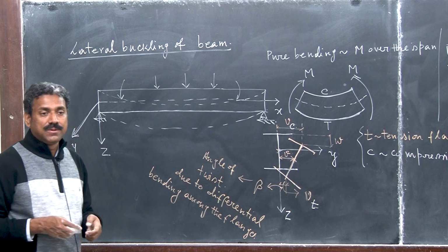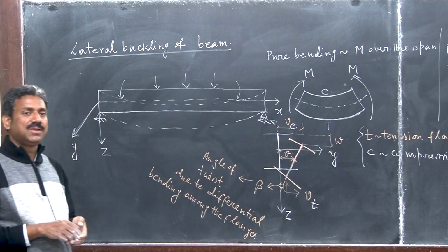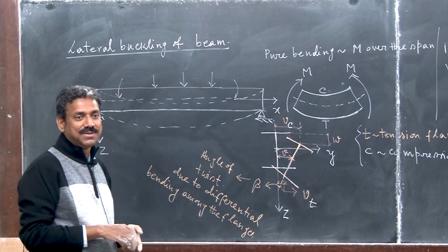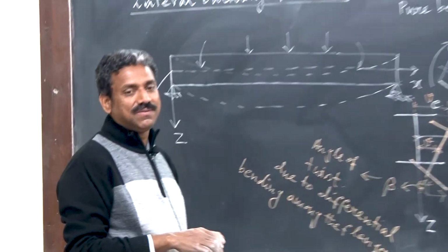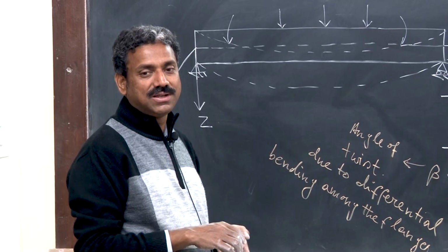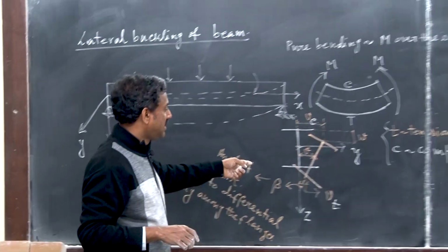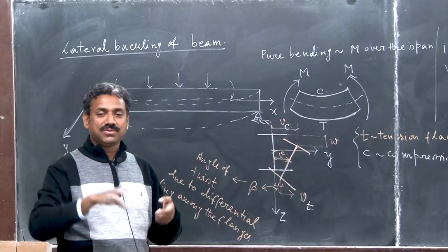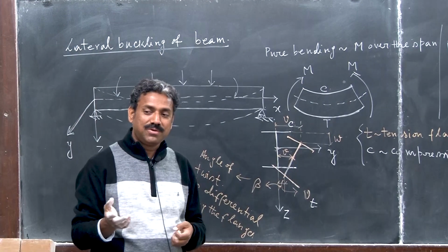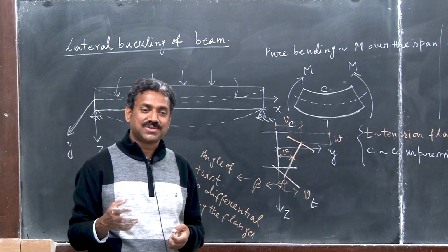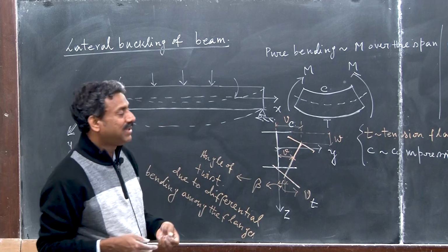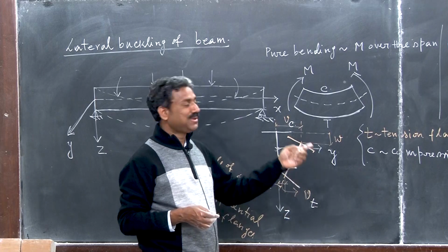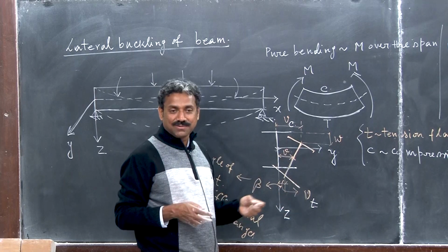And here we are not considering torsional flexural buckling, because we have considered that separately. We are considering that the section has both axes of symmetry. Now consider why the formula in your code was so complicated for the laterally unrestrained beam: at that time both lateral buckling and torsional flexural buckling were present, so you have to do a lot of calculation for the shear center.